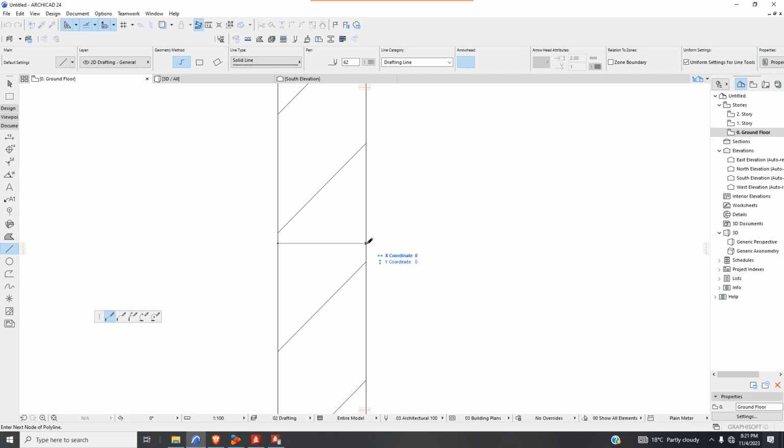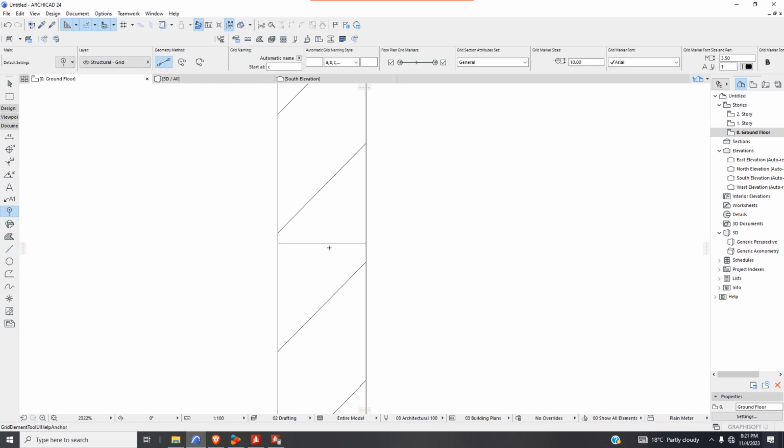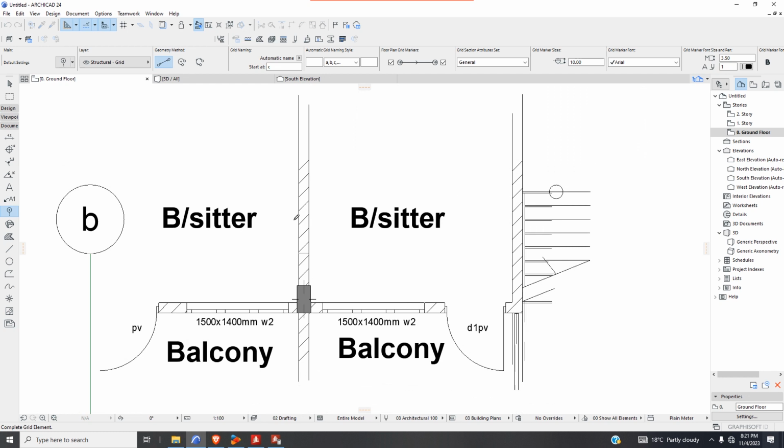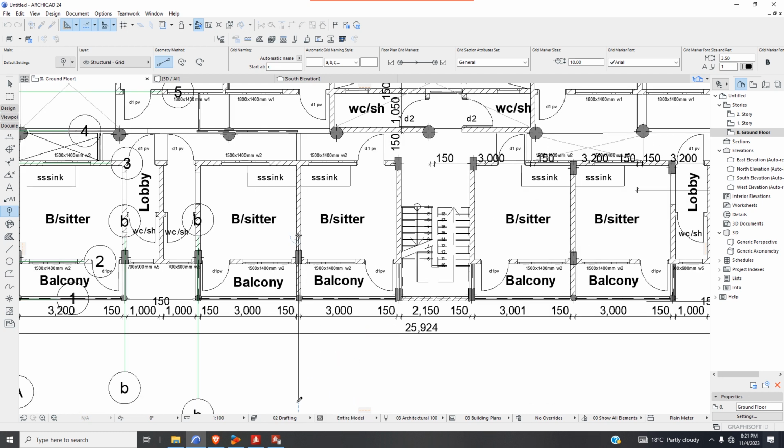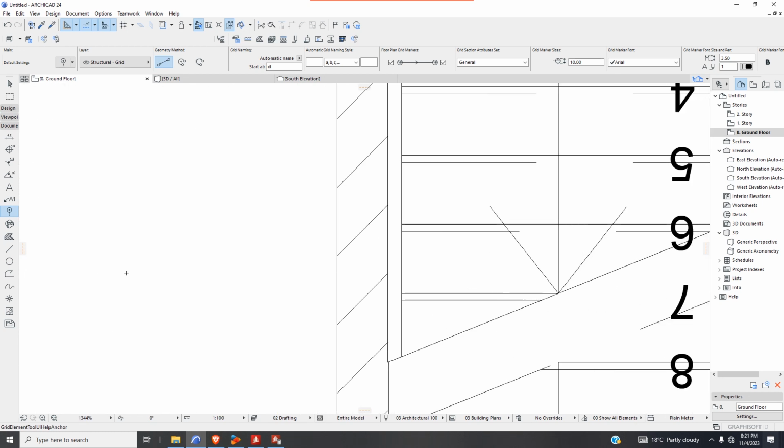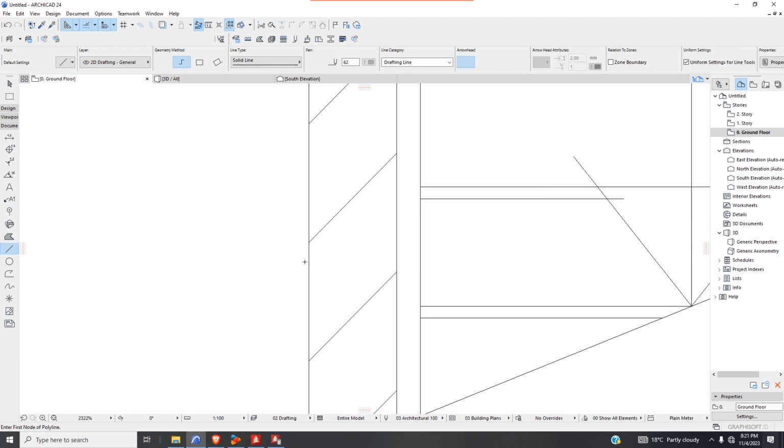now you can see carefully this wall is not in the same grid with this wall, right? So here you can just repeat this one column only in that direction by how many? I think 3.03 meters.